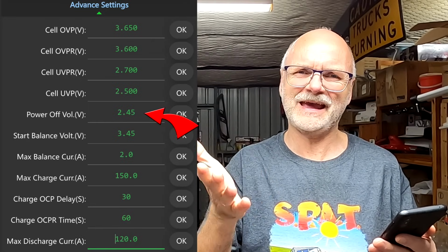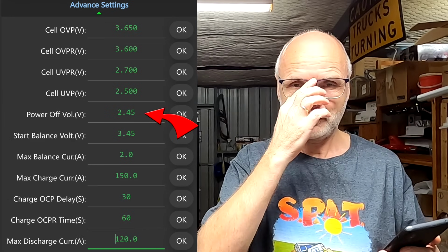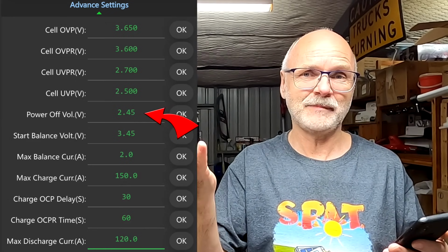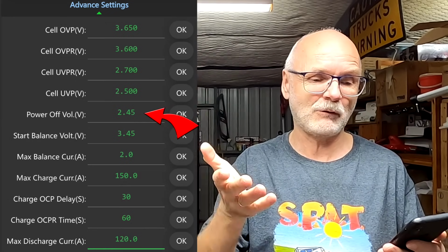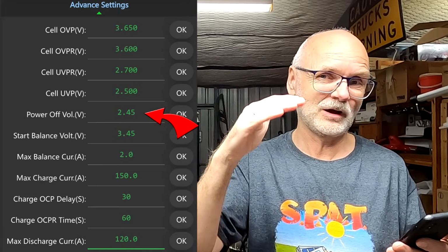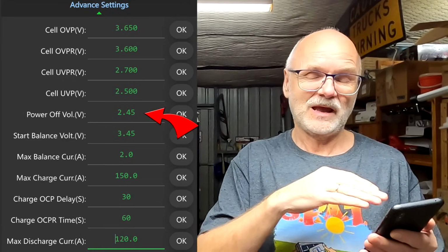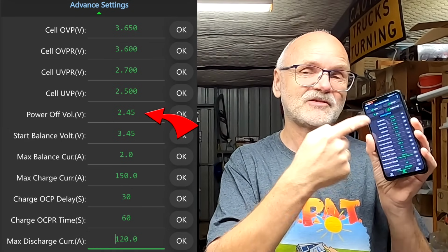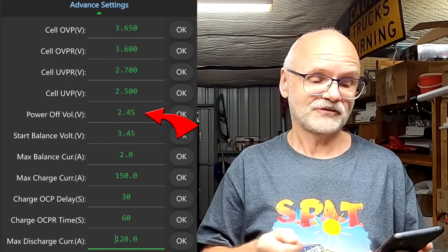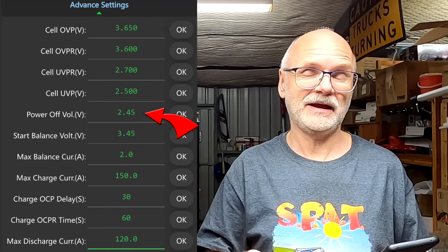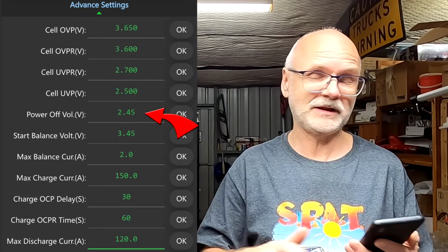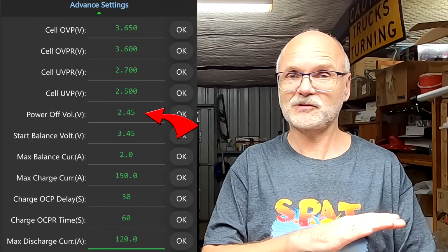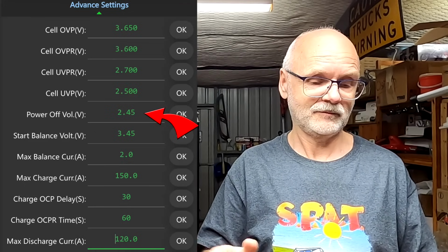You've got a cabin far, far away from everything, with a solar panel and a battery set up. In wintertime, maybe the solar panel doesn't bring any power into the battery and the battery goes lower, lower, lower. The BMS will turn off your load at 2.5 volts, but then the BMS still pulls power from your battery. So this is basically the voltage when the BMS shuts itself down completely, so there's no load on the battery anymore. Absolutely 0 amps, nothing anymore.